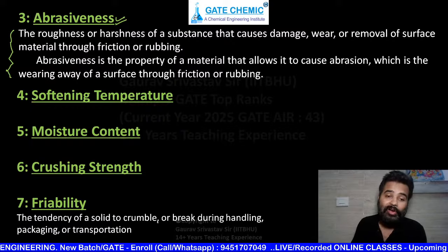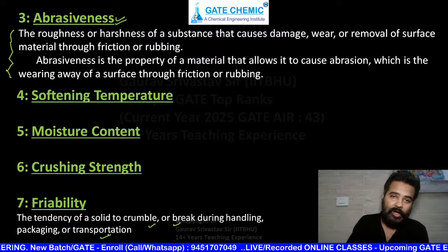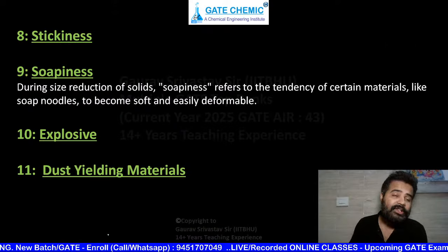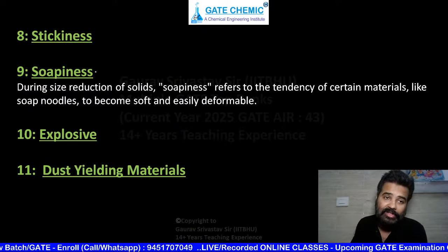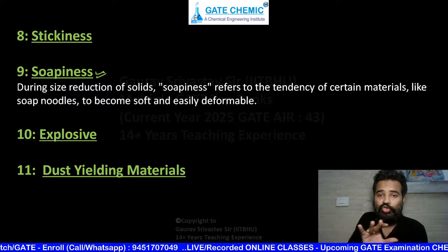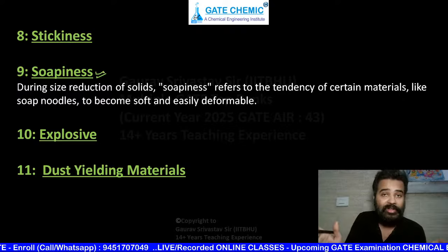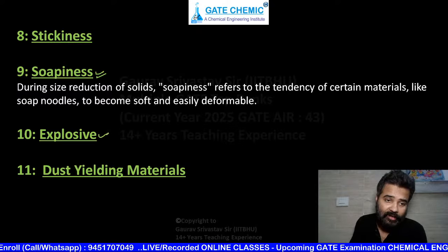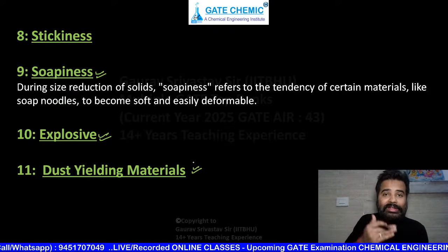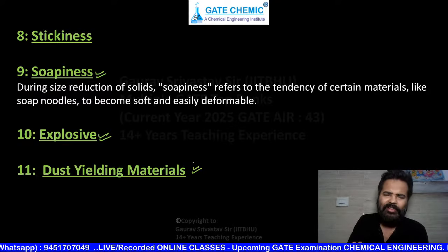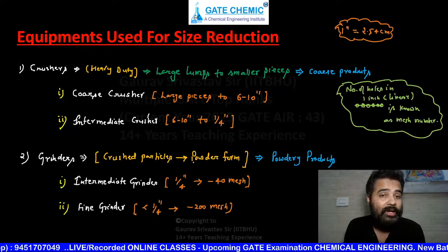Tendency of a solid to crumble, to break during handling, packaging or transportation. No need to write anything. Stickiness, that is, the solid is sticky or not. Soapiness, its nature towards soap or not. If it has properties like soap, then it can deform during size reduction. Its nature is explosive or not, and whether dust is there or not during size reduction. So these are factors that can affect size reduction, and again no need to write anything.